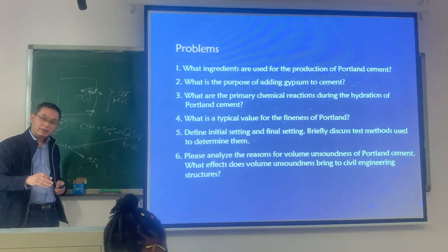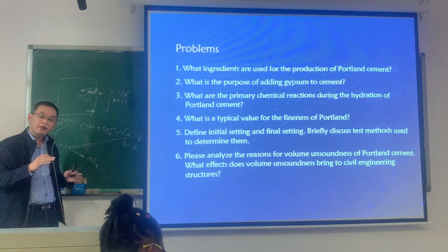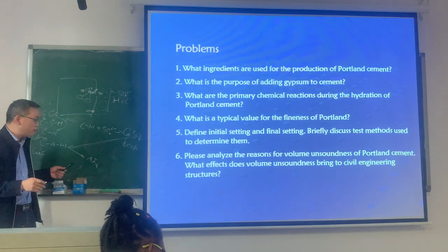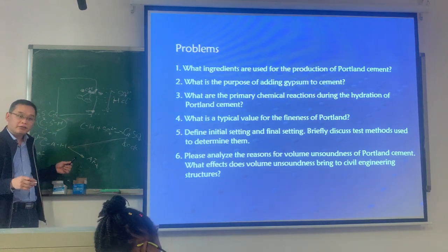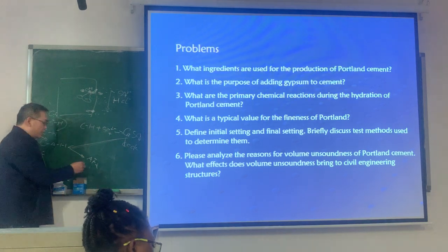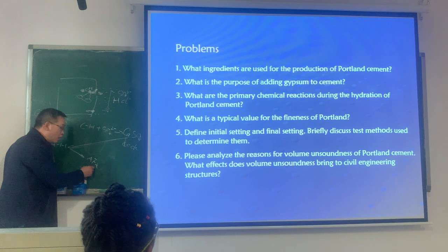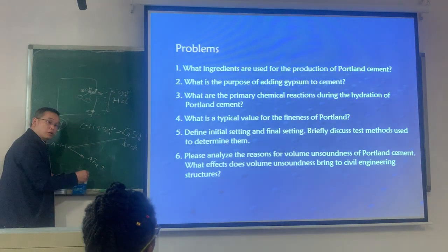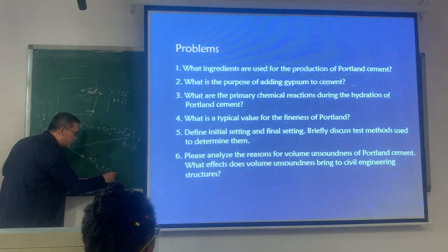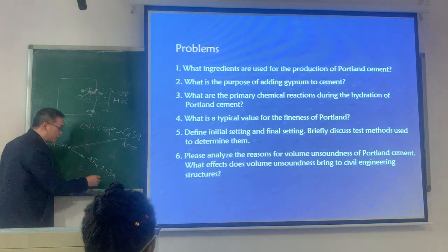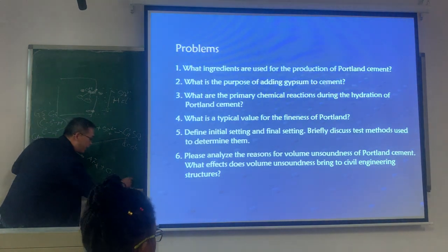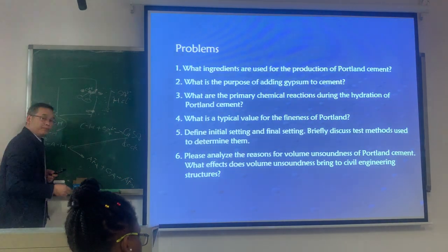And the amount of the gypsum must be optimal. If the gypsum is less, the AFt will react with the C3A. Get what? AFm.